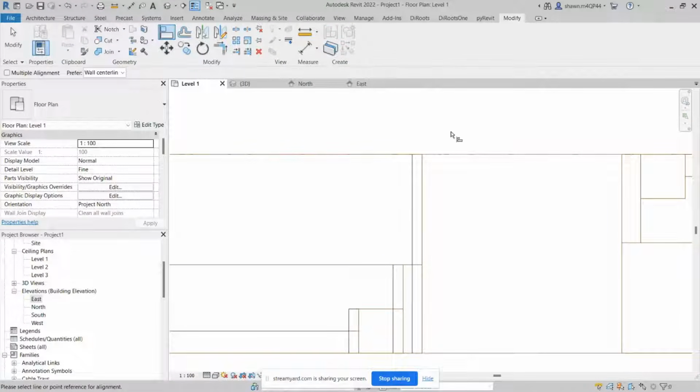If you're going to use Align, the first thing you do is select the reference. This might be confusing sometimes, but please always remember that the first click will be the reference. Then the second click will be the element you want to adjust.